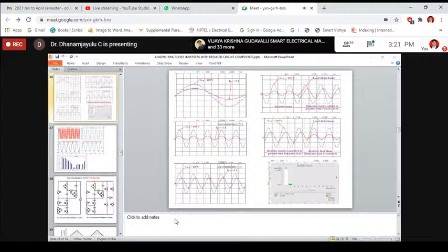My suggestion is, I think now you can take a SEPIC converter. By having a SEPIC converter, you have a secondary side with an inductor. By employing that inductor, you can get multiple output voltages. You can say single input and multiple output.